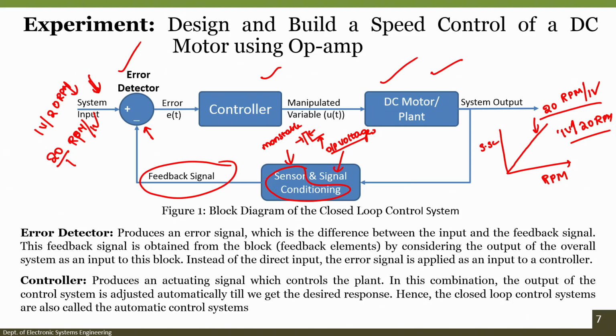We also understood that in order to do that, we have to design a signal conditioning circuit, and we have done the first part of the signal conditioning circuit to make a linear output by using an integrator as well as a monostable multivibrator, but the slopes are not matching with respect to the input slope. Then we have also designed the second set of signal conditioning circuit for the sensor, so that now the output of the complete circuit is mapping with respect to the input.